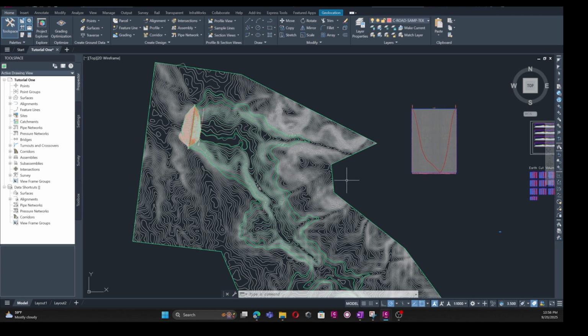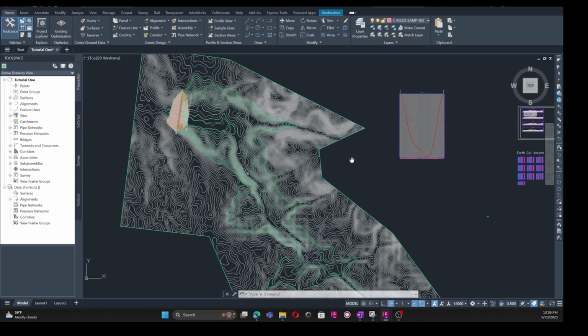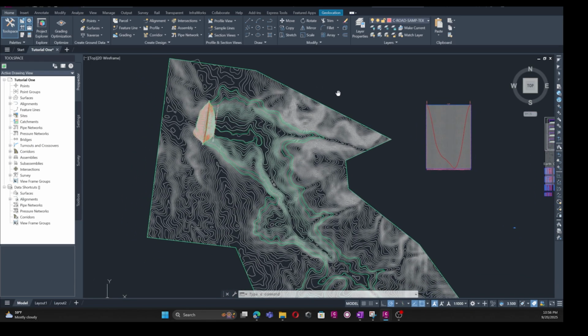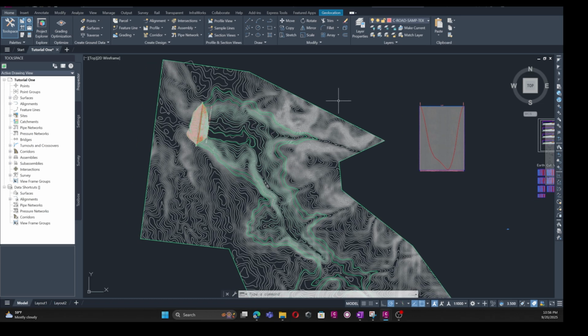When I say design, please note that all the required dimensions of the dam should be identified using geotechnical analysis in any of the geotechnical software like GeoStudio, in slope stability analysis as well as seepage analysis, and we have to have a safe dimension of the dam based on the provided standard and safety factor values.